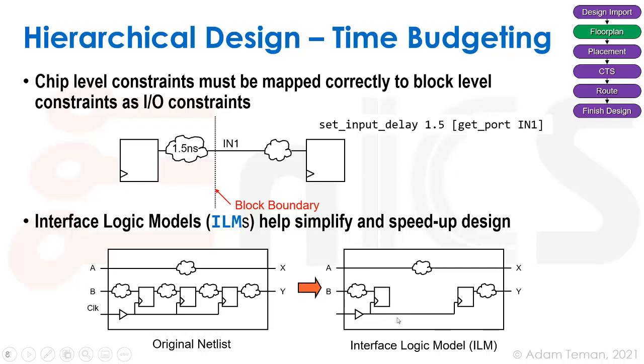And then I don't have a made up model. I have the real clock tree. I have the real delays that are going on inside here, and I can really do full static timing analysis on the other block. I don't have to do all kinds of modeling, wrong modeling of the other side.